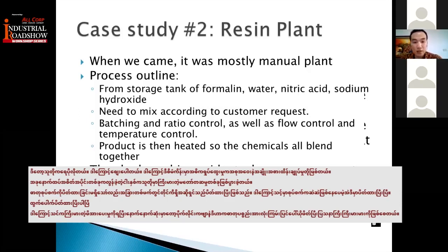Now, another component is that about 5 years ago, they had one big accident where the chemical pump was not turned off, but on the other side, the valve to the tank was already closed off. So you have this situation where the pump is still pumping, but the outlet is already closed.